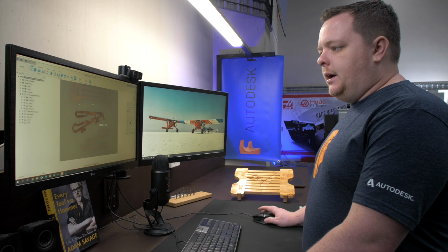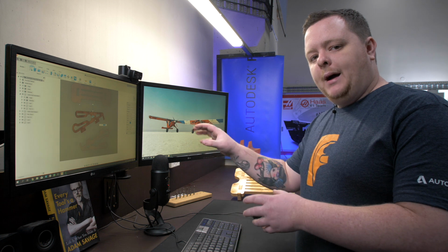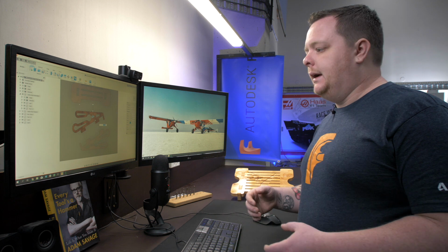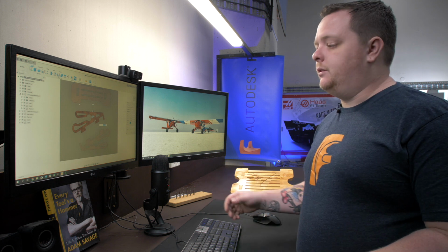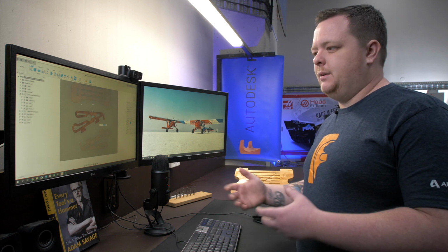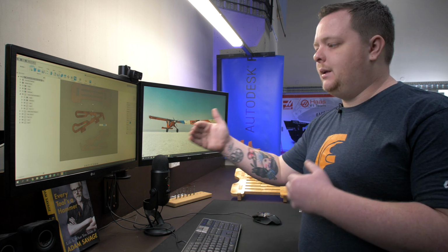We've definitely left a lot more margin around the top of the part and in between the parts than what we need, but there's no harm in doing that. If the stock is not going to be able to be used for really anything else, then you're probably better off leaving a little bit more space than otherwise you would normally do between the parts. But if you are wanting to use the stock in future, it's just something to bear in mind: am I going to reuse this later on? Do I need tight margins, or am I better off keeping a bigger gap?